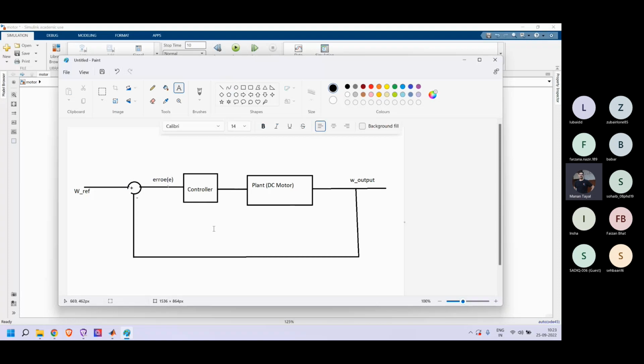and this is how this closed loop system actually works. There's also a sensor model which is generally kept here. So a sensor actually takes the value from the actual quantity and gives us the feedback of the signal, output signal, to the control system. So if in my case this plant is right now a motor, right? So we generally attach a sensor called encoder to the motors, right?